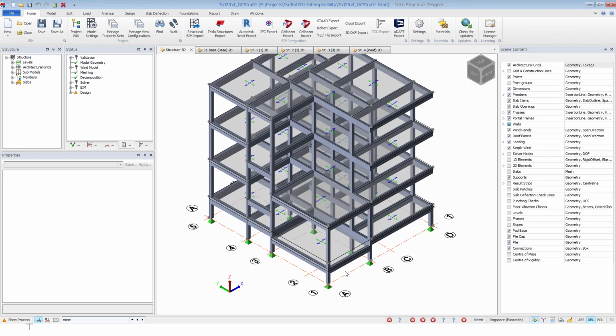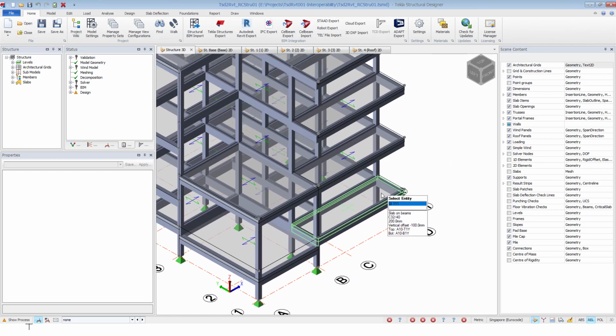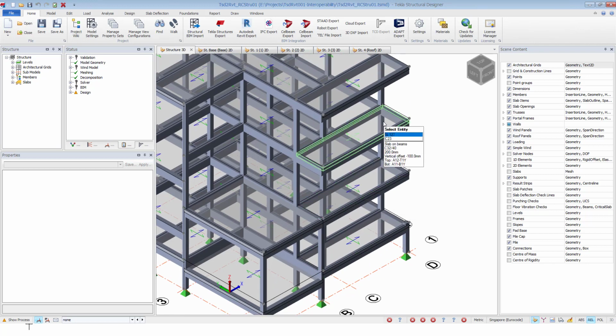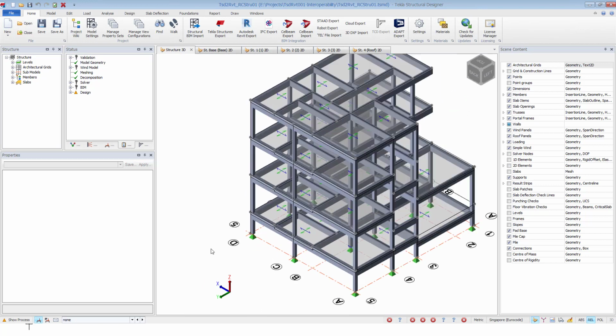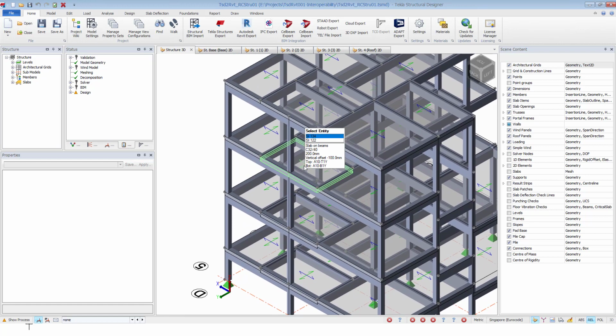Then we have some area. This area is actually the garage area. I try to offset down 600 from the main floor, and this is the entrance veranda, also 100 offset from the main floor, and the rest veranda also same thing, 100 offset from the main floor. And even toilet and bathroom also I try to offset this floor level 100 from the main level.